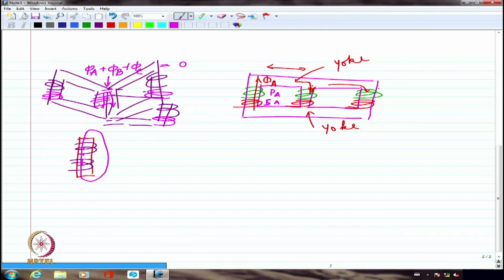So invariably, you would see that towards the distribution end, the fag end of the distribution, the secondary of the transformer invariably will be star, so that we will be able to derive single phase supply out of the final termination point, right? So much for the three-phase transformer.